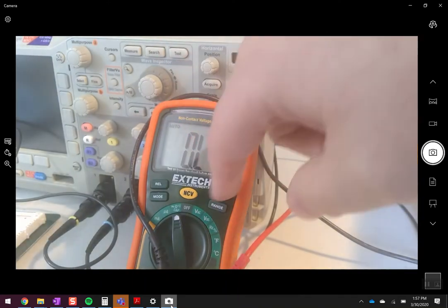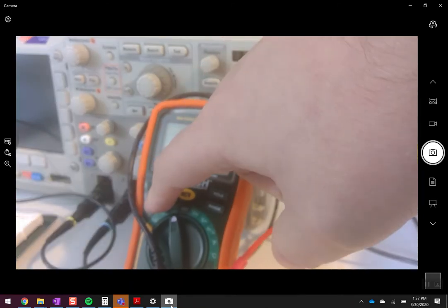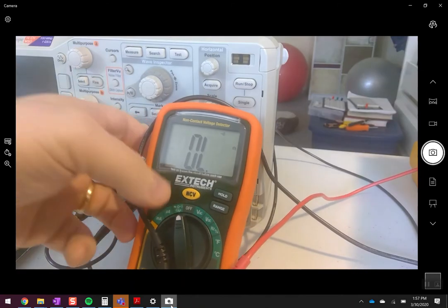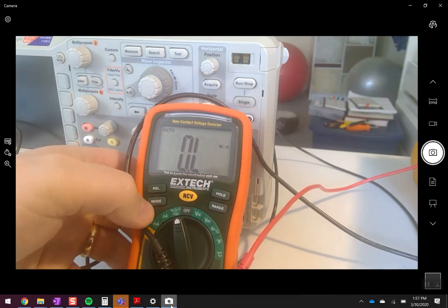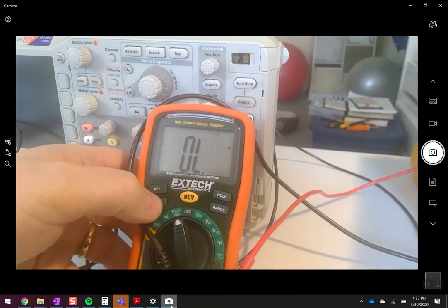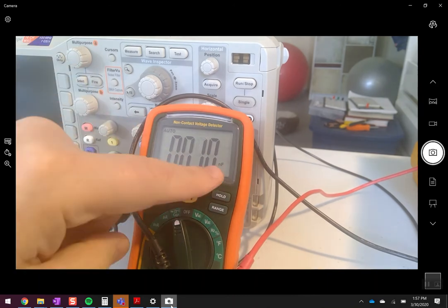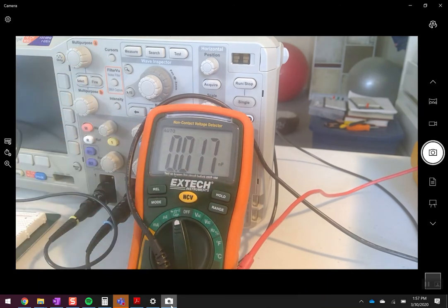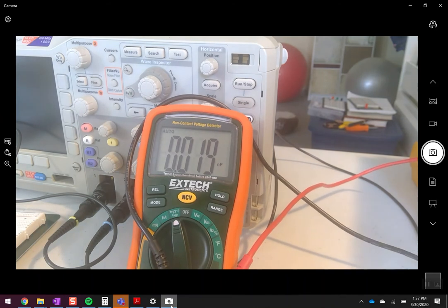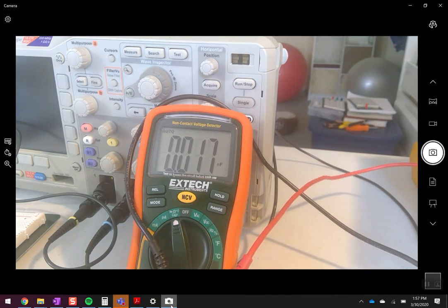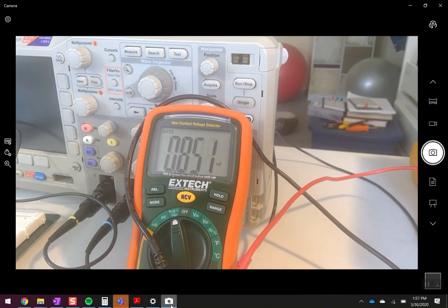And then this multimeter has the ability, I'm changing the mode here. I'm hitting the mode button several times. And then I get this where, notice that the units here are nF for nanofarads. And so I can actually measure, and again, this is what I do when I measure for your labs. I can measure what this is.